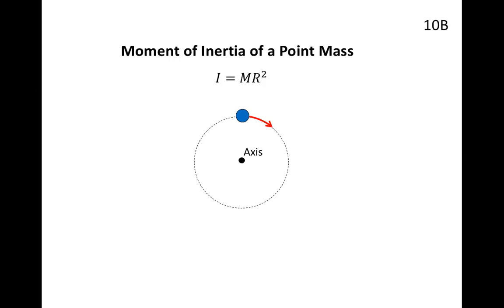Well, it turns out the mass is multiplied by r squared to give the effect of inertia in this rotating scale. This makes sense, kind of, because to get alpha from acceleration, you had to divide by r. You can imagine on the other side, you'll be multiplying by r to get the force, to get the torque. We've already actually done that. And so if you think about F equals ma and what you have to do to make that work, the r squared makes perfect sense for this point mass from an axis. So this is the simplest case.